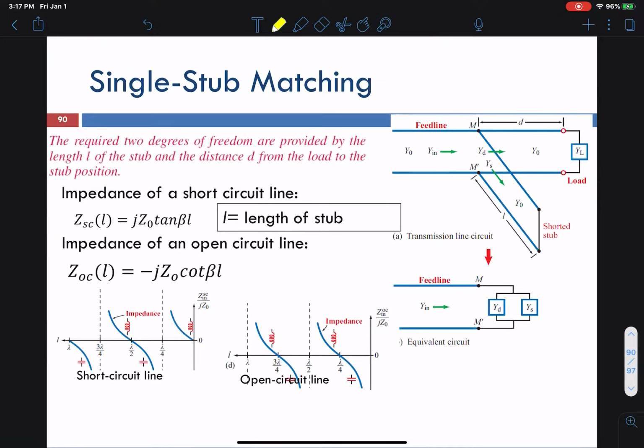In the last lecture, we showed you that you can match the load with the characteristic impedance of the line to minimize the reflection from the load. That happens with what we did last time: we add a reactive part, either an inductor or a capacitor, at this point over here, distance d from the load, to match it. So if you look from here now that way, your y in would be equal to y0. That means you perfectly matched, right?